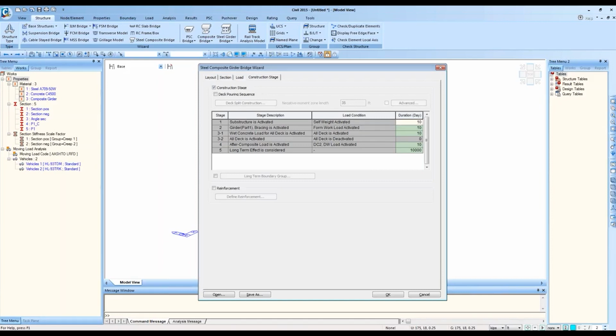So once the self-weight is activated, you don't need to deactivate or activate again for other parts of the structure. By default, the self-weight function will be calculating the weight of each component according to its section and material property. Once you activate it, it stays there. And as other parts of the structure are activated, automatically their material and section will be counted toward the self-weight calculation.